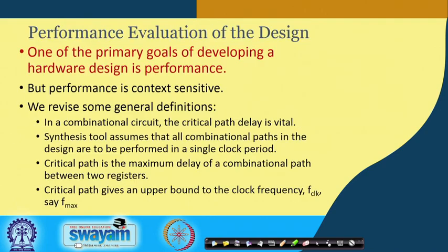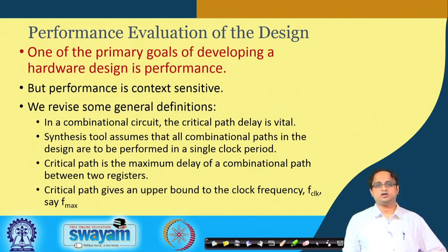So now we essentially come to the next part, the exploratory part, where you have to do a performance evaluation of the design, because as I say, one of the primary goals of developing a hardware design is performance. Okay. But performance is context sensitive: depending upon your application, you may want to make it low power, or you want to make it fast, or maybe the objectives are different. But broadly, in a combinational circuit, the most important aspect you want to optimize is the critical path delay. Okay. The critical path delay is often predicted by the synthesis tool, which tells you, from register to register, what is the maximum path.